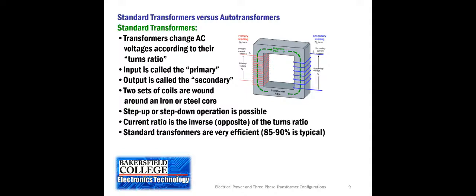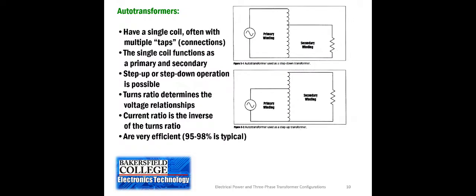So it takes up or utilizes, and they will have different taps that not only can you use to create exactly the voltage range you want, depending upon what the voltage coming into the transformer is, but also by changing whether the primary is a delta or a Y and the secondary is a delta or Y, you can further get a different set of voltages. Now, with an autotransformer, they only have a single coil, and that single coil has multiple taps in it.